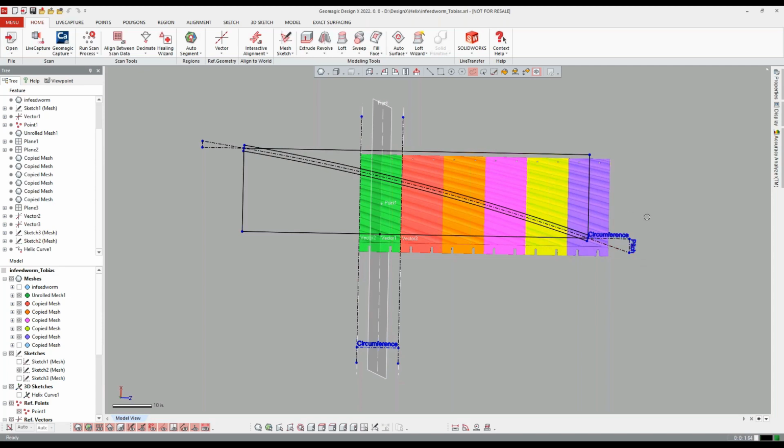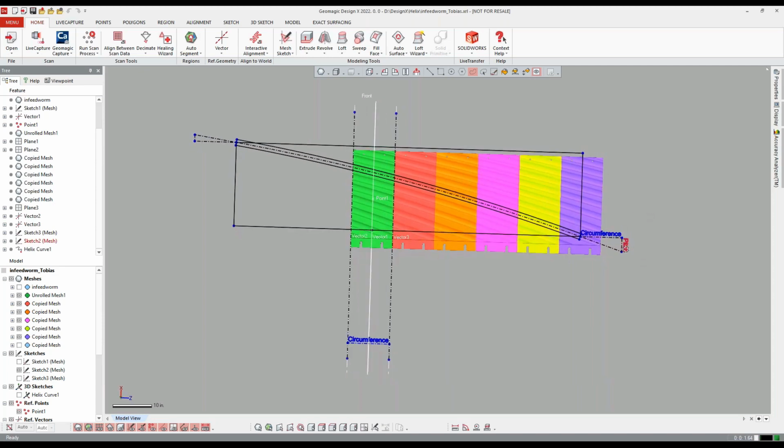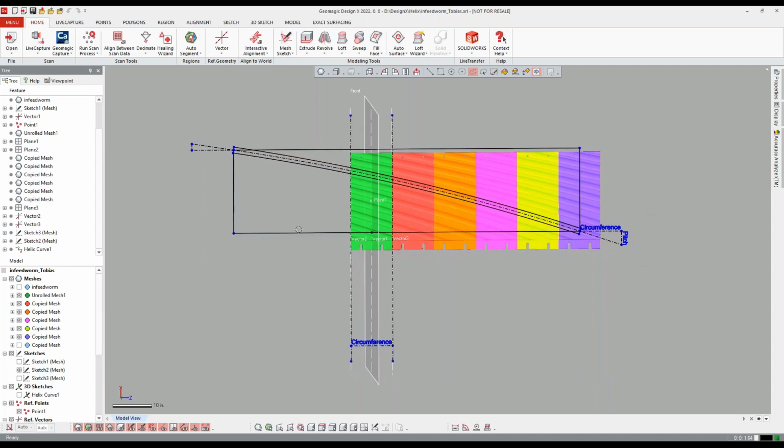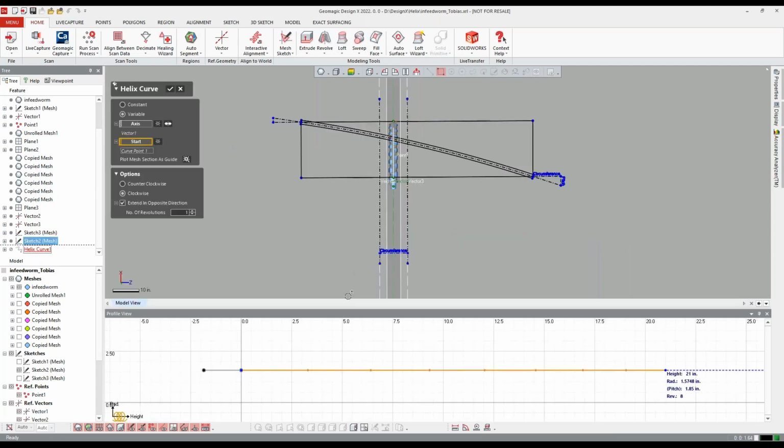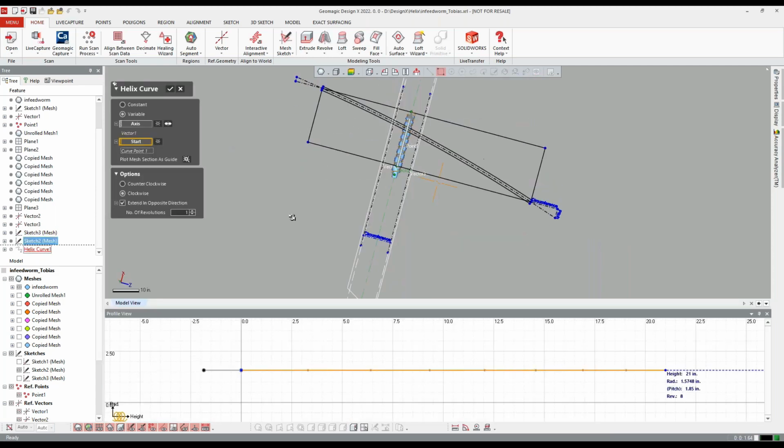So this is just a quick way to figure this out with some math here and get your in and out pitch. If you start your start height on one end and the end height on the other end, and you look at your pitches coming off at those two heights, then you know what your start and end pitch is. We can feed that back into the helix tool, okay? At that point, with our start and end pitches, I'm not going to specify every point.